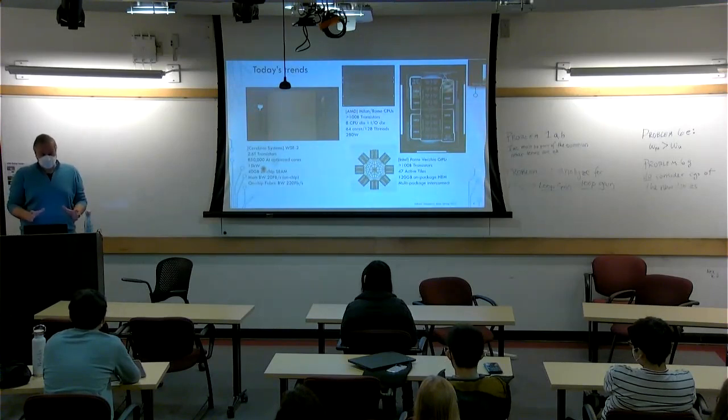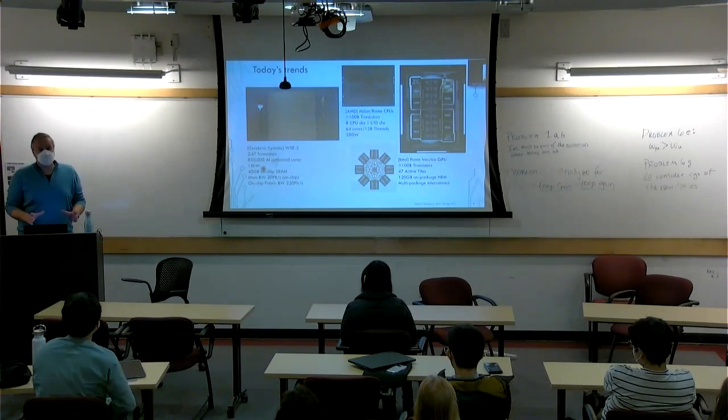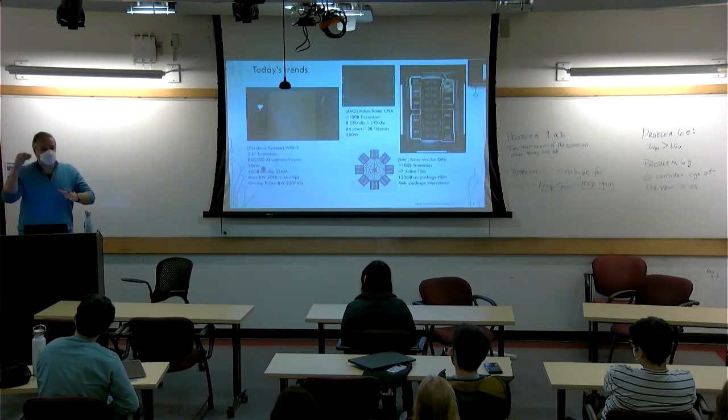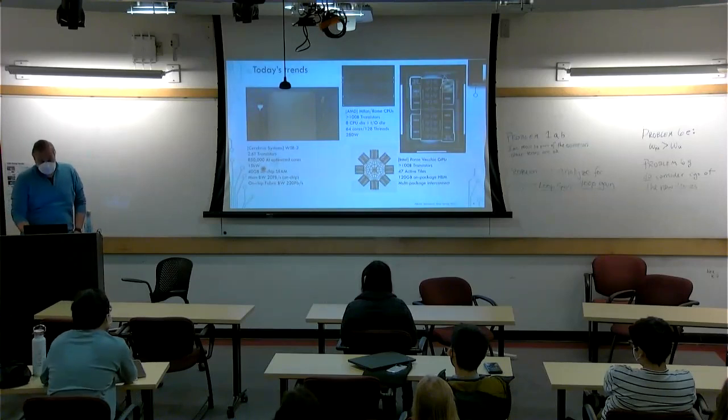So how do you deliver at 1 volt of supply? This is 15,000 amps. That's like a copper pipe this thick, just to attach to this to provide current, right? These are some really crazy numbers, but people have built it. And because of that, they can add a lot of SRAM to the chip itself. 40 gigabytes.